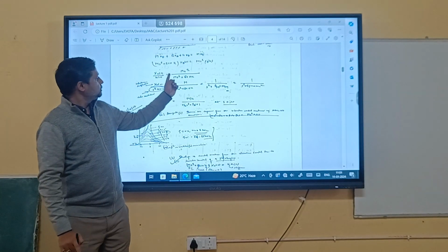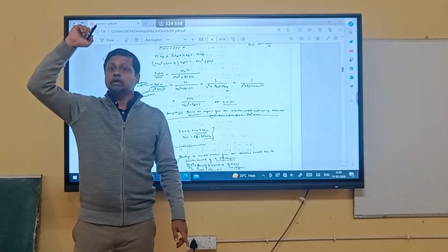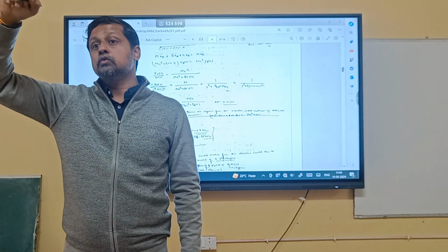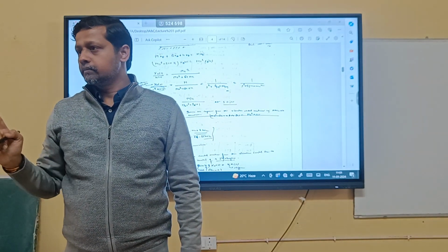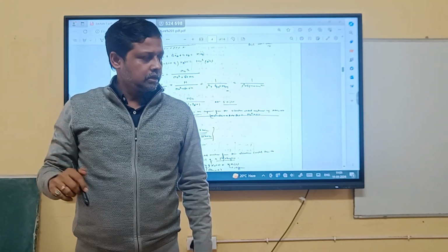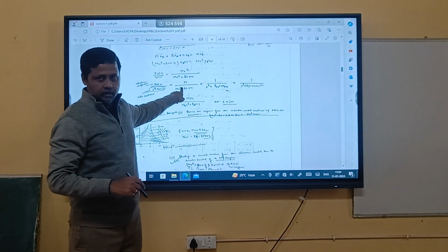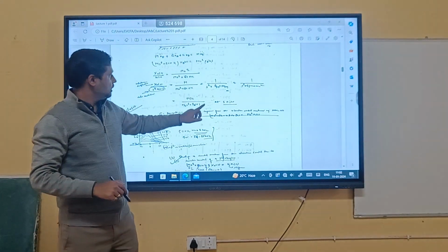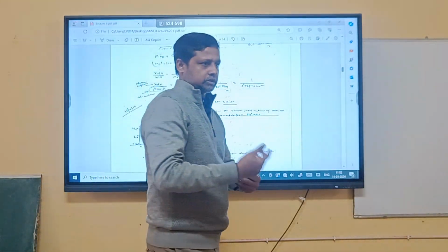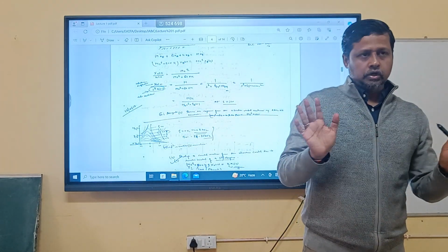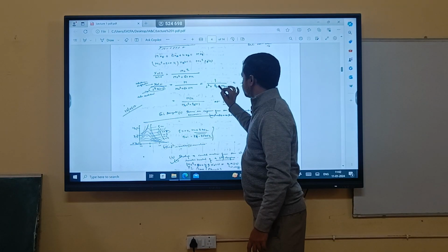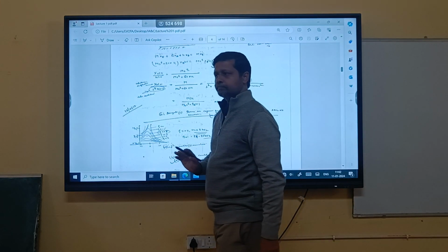Until you modify it, remember one more thing we have already discussed. It doesn't matter whatever your equation is, always bring the highest order coefficient to 1. We discussed this a number of times whenever we do mathematical calculations. So what is the highest order here? s square. Remodify the equation further so that this coefficient is 1. Just bring it here. Do these calculations. So by doing that, can I get this equation? 1 upon s square plus b by m into s plus a by m.